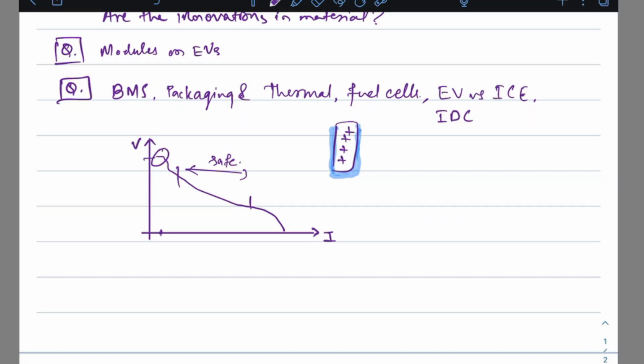The idea behind driving cycles is that you can utilize them to predict how your vehicle will behave in real-world scenarios. These driving cycles are somewhat standardized to mimic, say, city driving conditions or highway driving conditions of a typical vehicle which will move on our roads. Given it's our Indian roads and our traffic, we cannot just directly borrow someone else's driving cycle and use it.